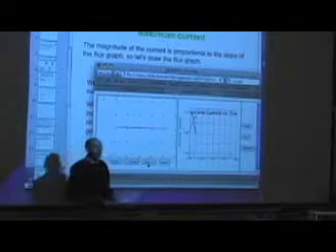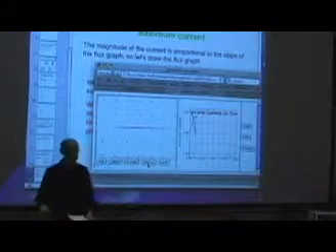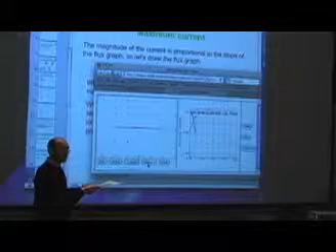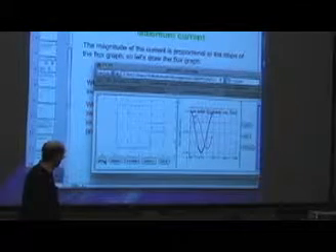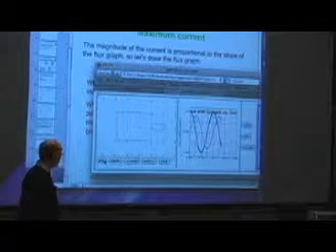You're actually changing the flux most quickly at that orientation. So the flux is actually 0 there, but the change in flux, that's the key, is the highest you get. So strangely enough, it's where the flux is 0 that you get the peak current, because you're changing the flux most quickly.